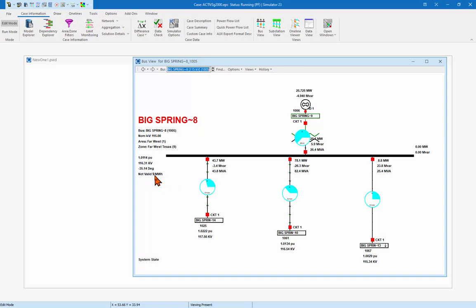The next display is an optimal power flow quantity for the megawatt marginal price. That's not valid because we haven't solved the optimal power flow, so that's why that's shown. And then we also see real and reactive flows to each line, and the bus voltage magnitude and kV voltage of the neighboring buses.